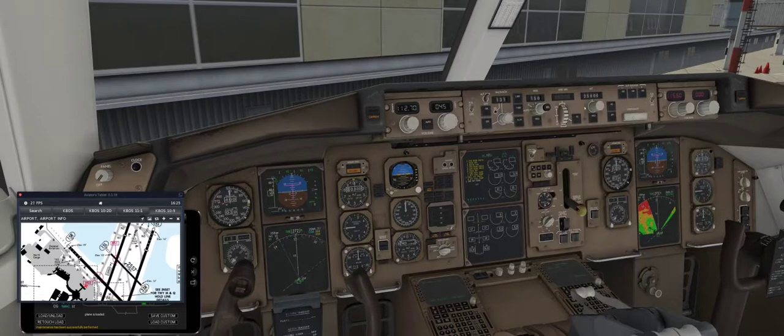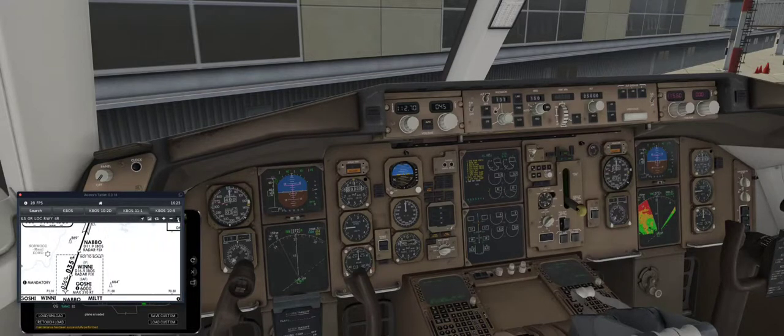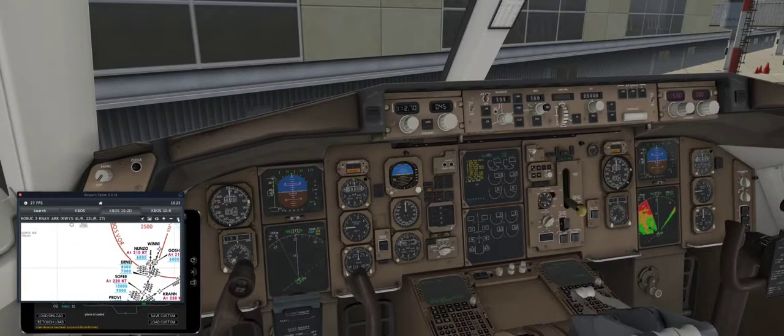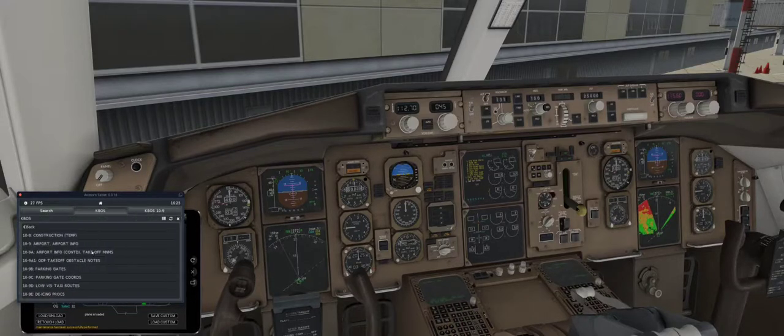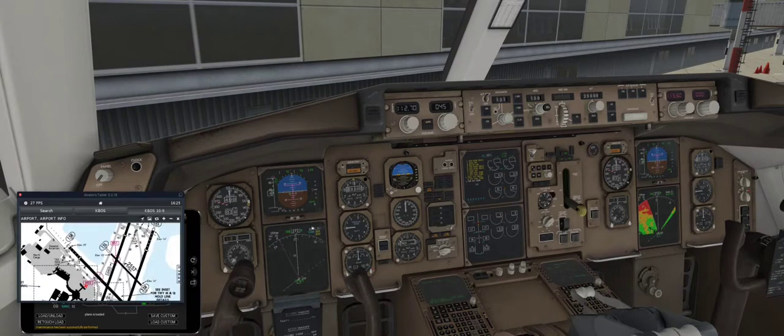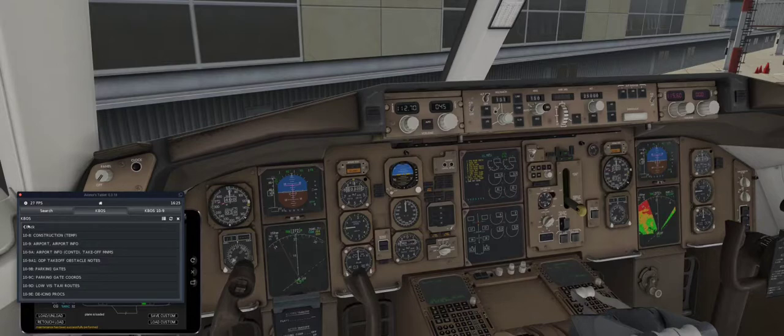And make sure that's engaged. Your flight directors are on. And at this point, it's probably improper, inappropriate, but I was going to say you should be able to engage your LNAV and VNAV right here, but apparently you can't. I usually do that while I taxi, so we'll come back to that. We don't need this approach, we don't need that, but we do need, what did we need over here? Yes, we needed to get a departure.